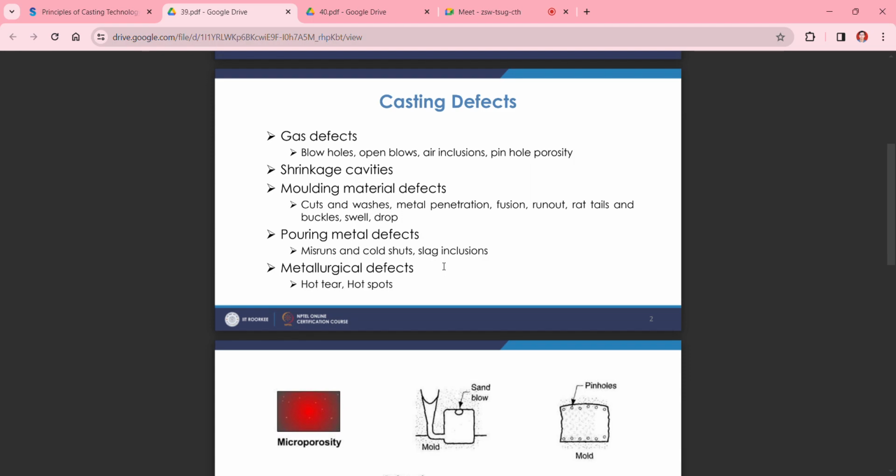Okay, so in the final casting, that solidified metal on the surface is going to come with your casting. To remove that defect, you have to provide some fettling or something like that. You have to cut it out, you have to grind it out from your final design, so you can get your desired casting.